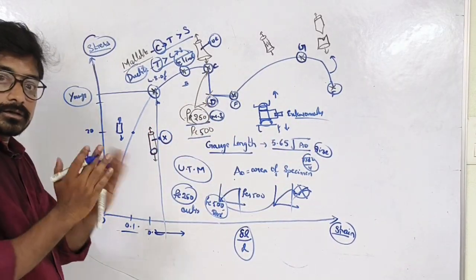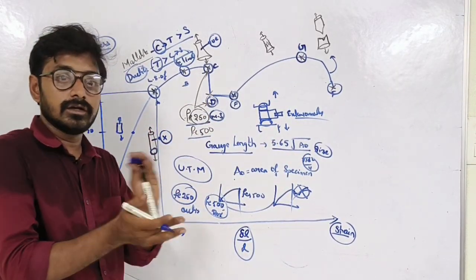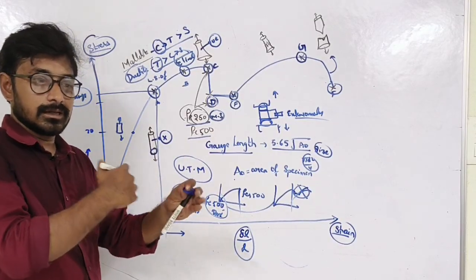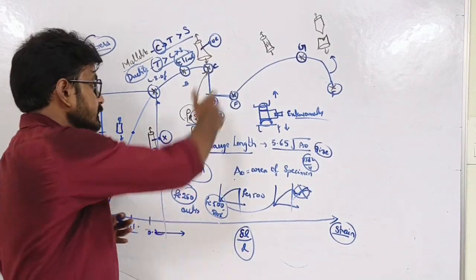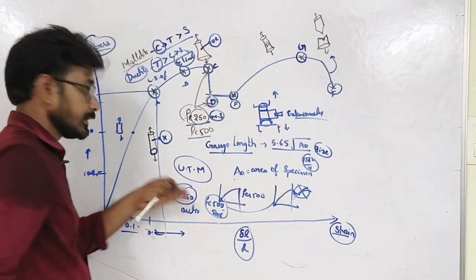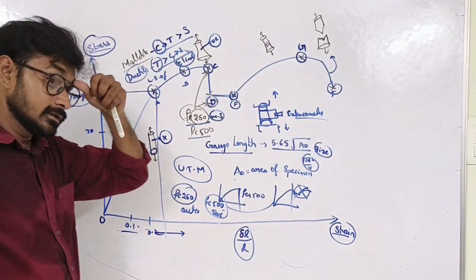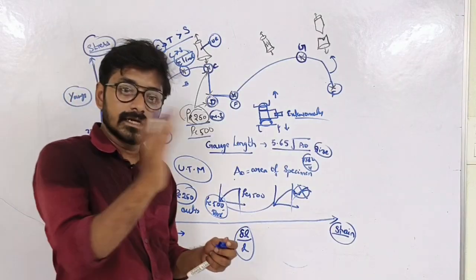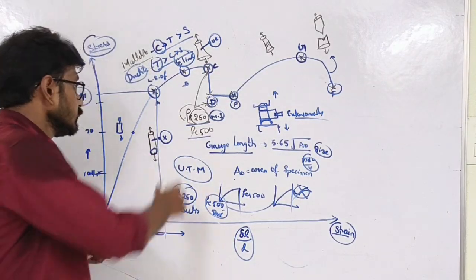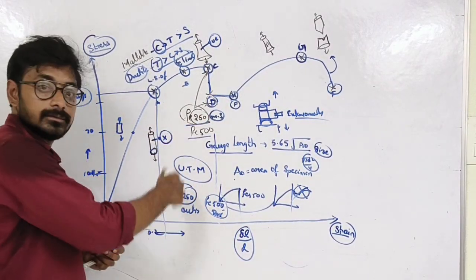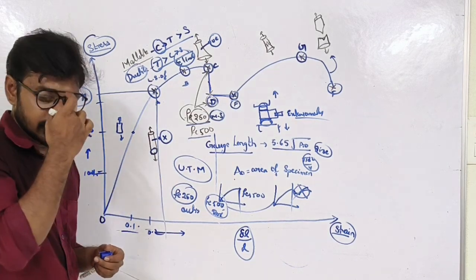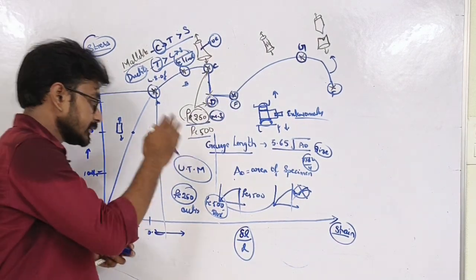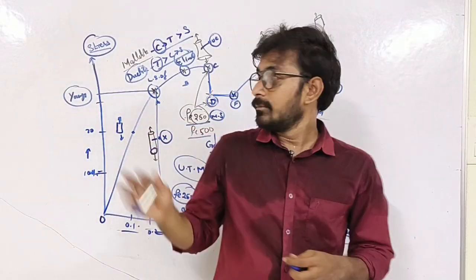Which type of material will take more stress, a more elastic zone, that is all this stress strain area, is considered as ductile material. But whereas in brittle material there will be a sudden failure because they don't have much area below the yield zone, before the failure zone. So that's why we will consider it as brittle material.